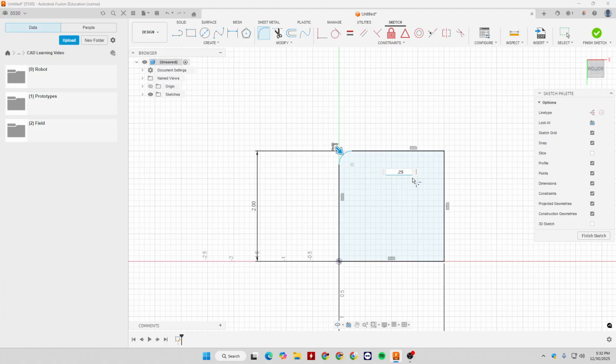If we do 0.25, it will become even smaller. And then we can do up to the actual side length of this. So if we did 2 inches, the radius of that would be that full side. But we're usually not going to do things like that. So 0.5, that'll allow us to make edges smooth, machining them easier, stuff like that. This will give you the tangent constraint. It's kind of creating a circle inside here and then trimming it down is essentially what this does. And then you can edit that radius by changing this. Double clicking is how you access that.